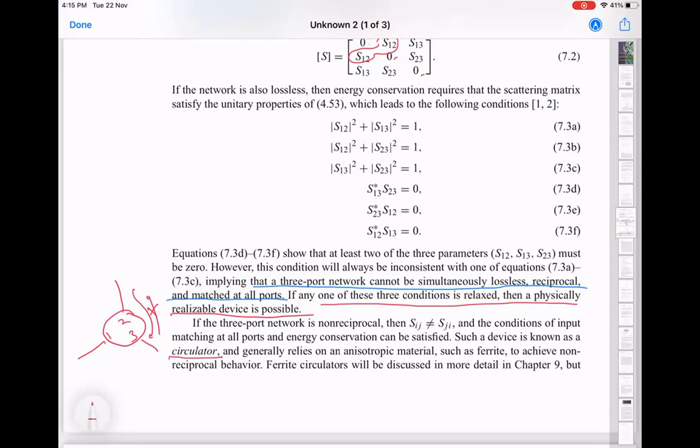So you want the signal to go this way, but there is some noise coming this way, which you would not like to reach your device. So these are the two main purposes for which they are used in these cryogenic experiments. And these circulators, even though they do the job, they are bulky and they can have losses, a little bit of loss as well, which sometimes can be an issue.